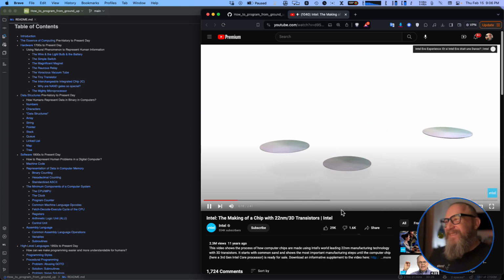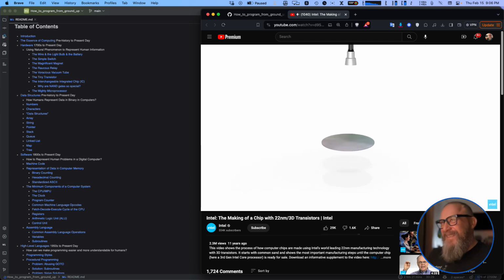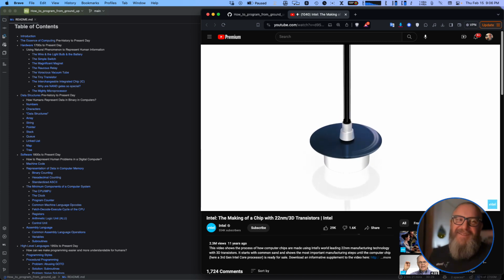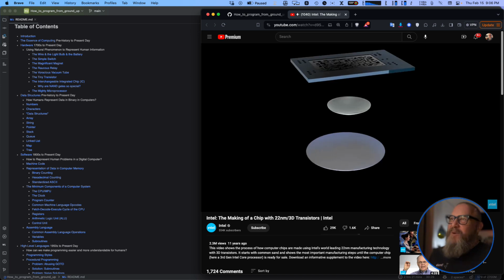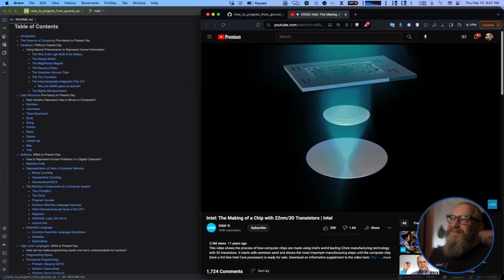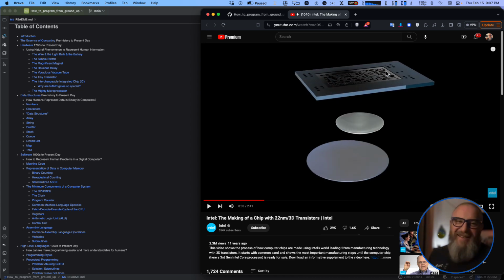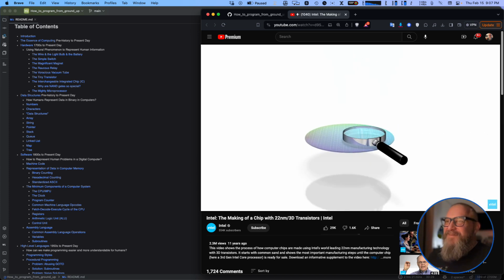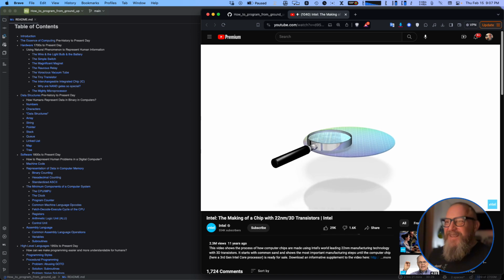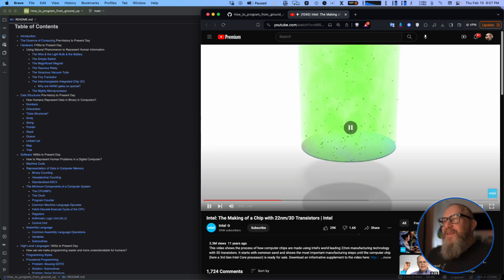They slice it up into wafers, and they coat it with some base chemical, and then they take the pattern that he's got here, and they change the surface using ultraviolet to give all the little circuits layers, and they emit a gas that layers down very softly, gently, and it has to be really smooth.